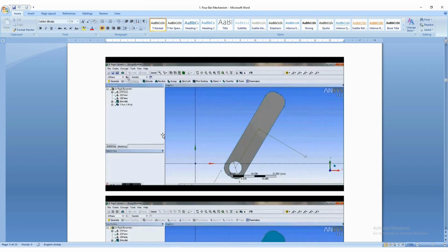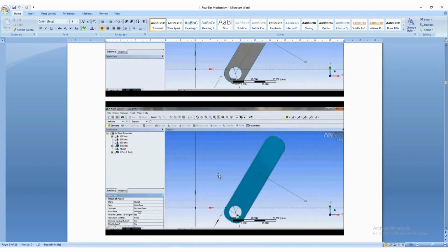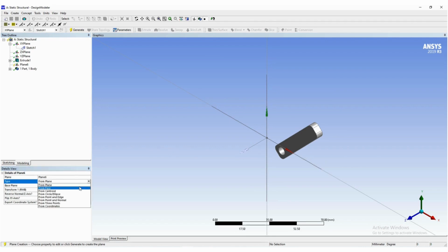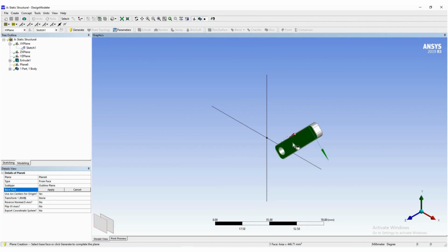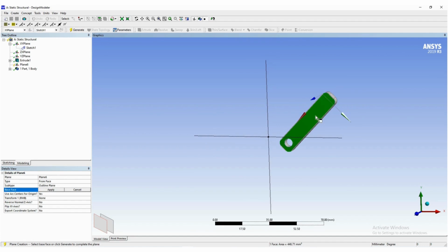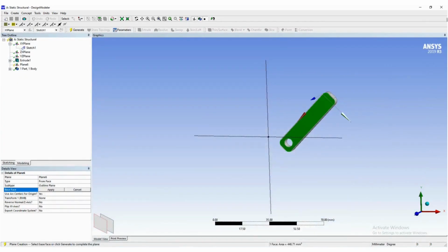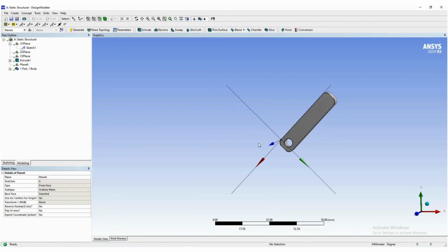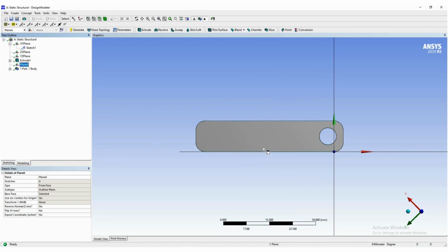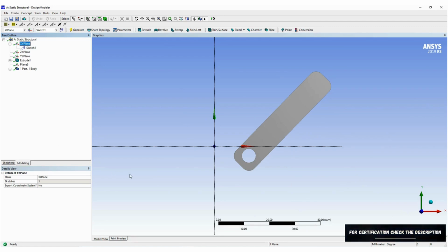So we are here now. Now we will select this plane for sketching, or here I'll go on to create plane creation. Then from face we have to create. So here face we have to select this face. Now if I select this face, you can notice this face selection will appear here, and simply if we see, we can just select that one, just apply it, or you can select here so that this axis system will come over here, and select on to apply, and just generate this. Okay, so this plane is selected. Now I'll make this plane look at. Okay, and if you see here, this one is there, or simply you can go here and make this as a look at.